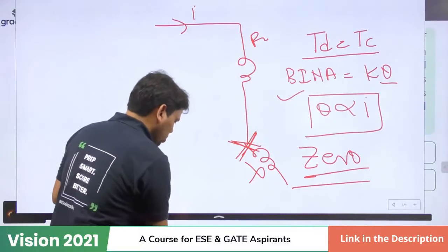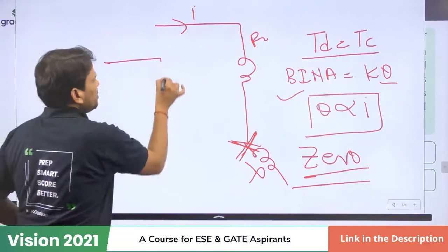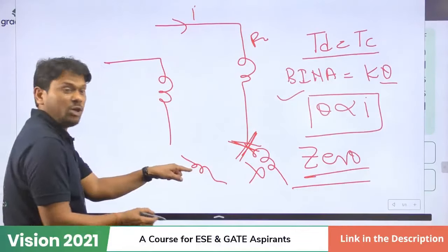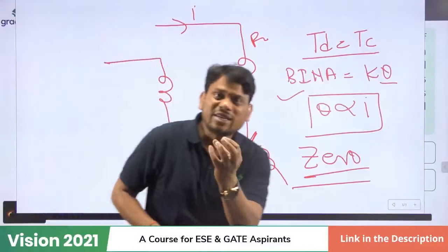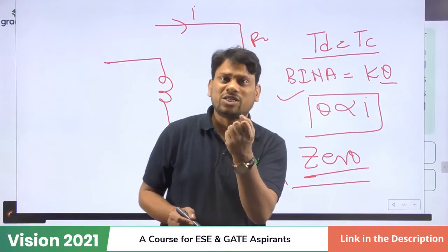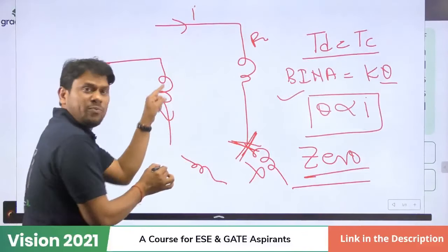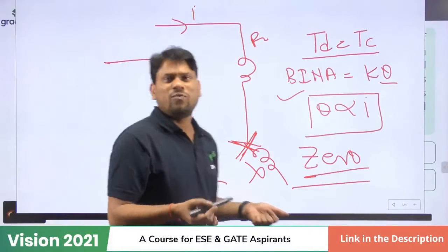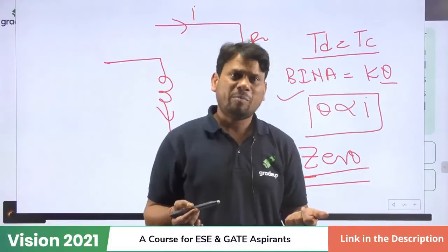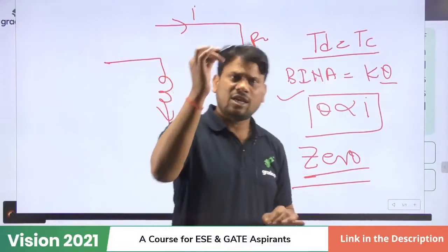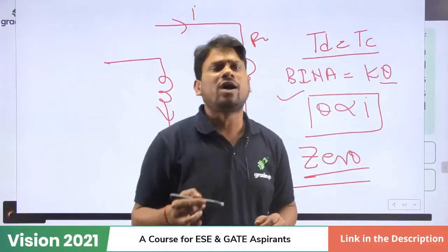This is our moving coil, and somewhere here we have a spring, which is directly connected with the moving coil. Please try to understand. Now, if our spring has been broken, then no current will flow through the moving coil, practically. Try to understand. So here the reading will be 0. Yes, obviously, absolutely, all of you are right.